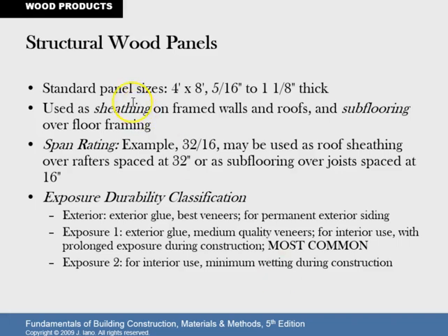Okay, so standard sizes for these sheet goods. Standard panel size, 4x8, is the size of the actual sheet, and thicknesses range from as little as 5/16, or a quarter inch, or actually less than that, up to an inch plus. They can be very thick. Used as sheathing, so this is the outside of our rough framed buildings, and as subflooring.